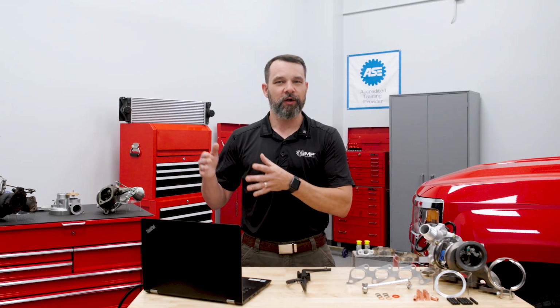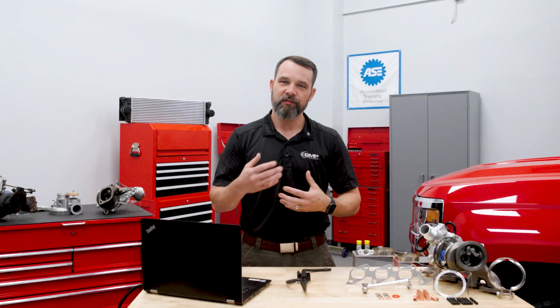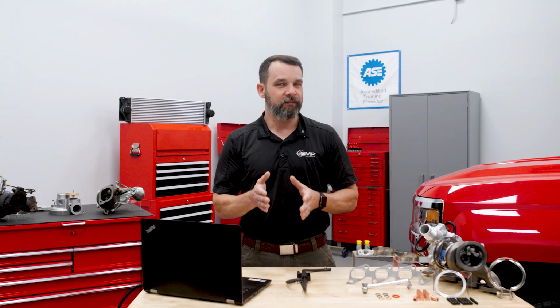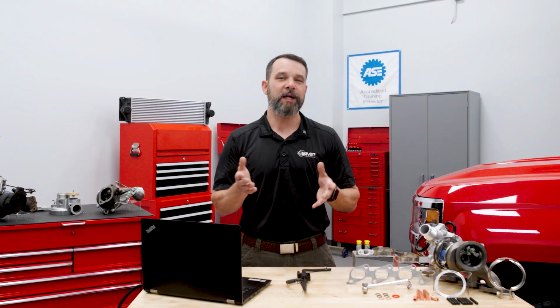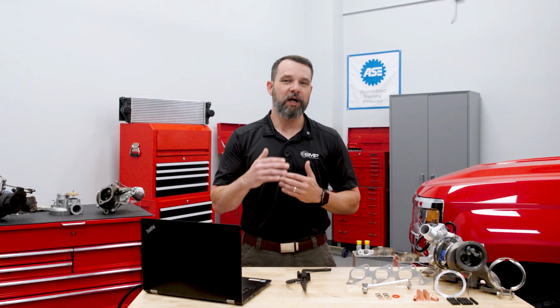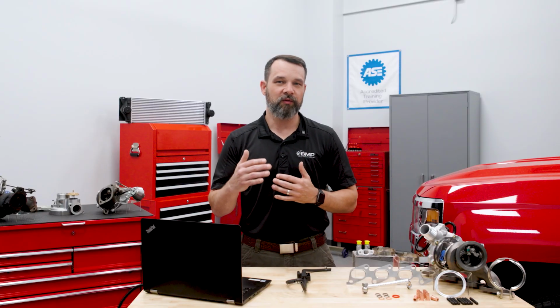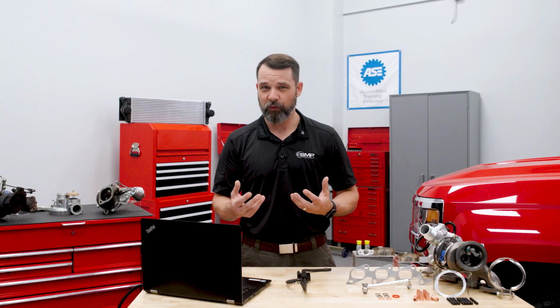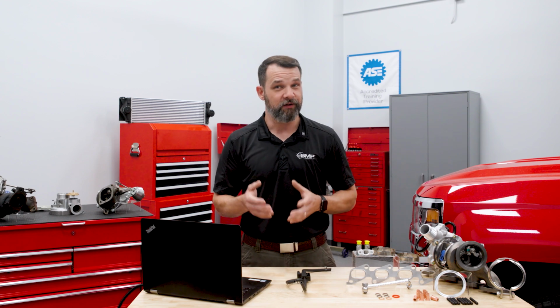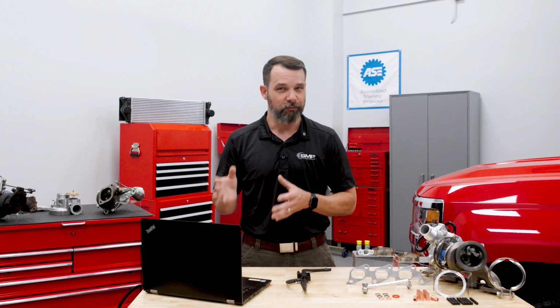But we started working on other components, and then we were doing some test drives. And oddly enough, around 54, 55 miles an hour, it didn't matter how much weight you put on the accelerator pedal, that was as fast as it was going. It was not going to get any more power whatsoever. We were losing boost somewhere. We didn't know where it was, but we went back to that code, and sure enough, it's telling us, hey, you got an issue related to your boost.